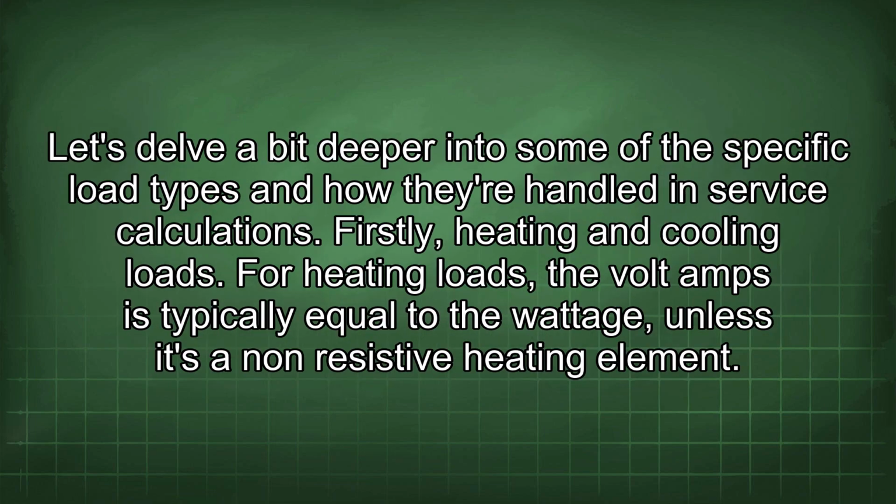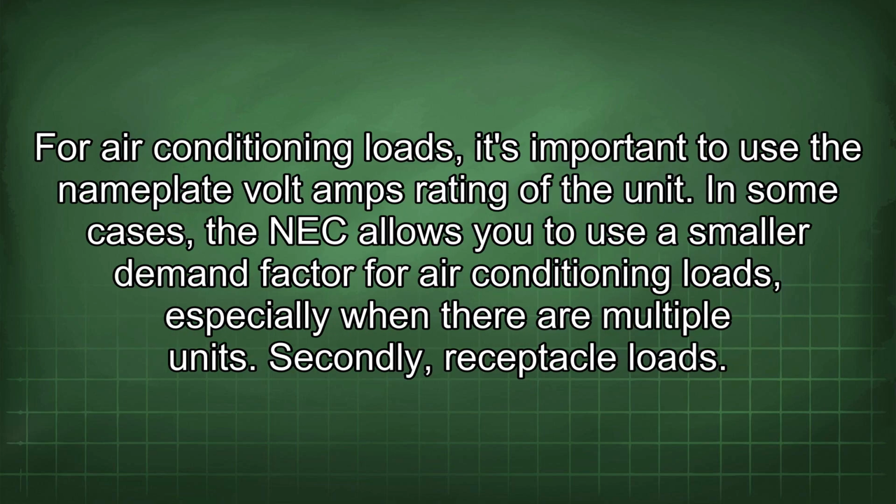Let's delve a bit deeper into some of the specific load types and how they're handled in service calculations. Firstly, heating and cooling loads. For heating loads, the volt amps is typically equal to the wattage unless it's a non-resistive heating element. For air conditioning loads, it's important to use the nameplate volt amps rating of the unit.